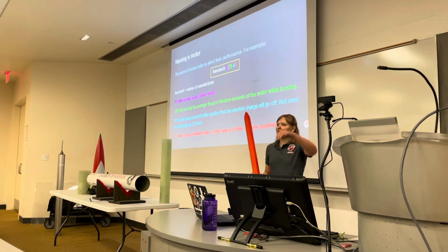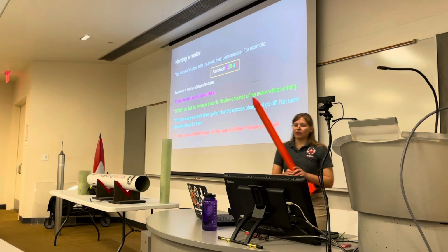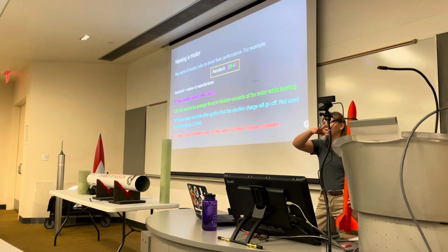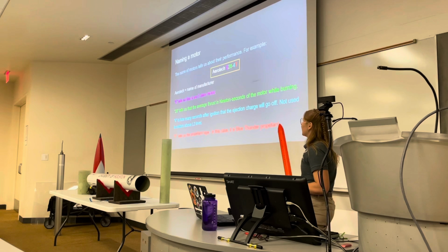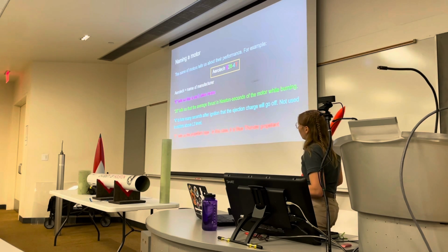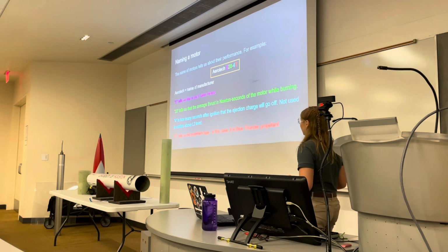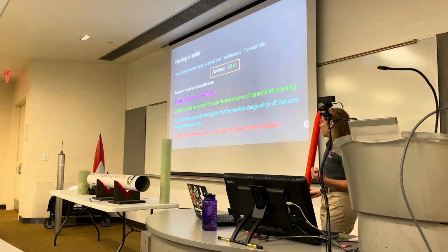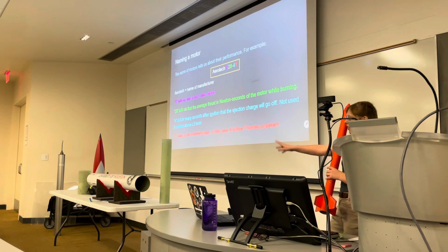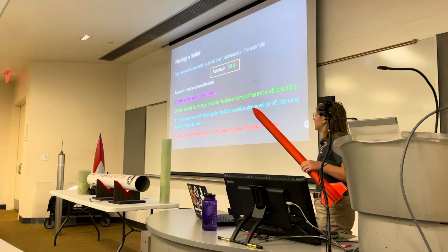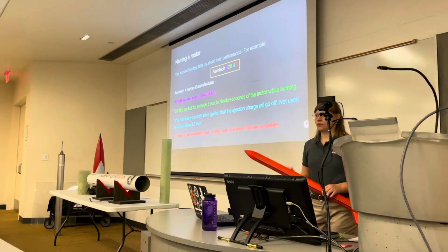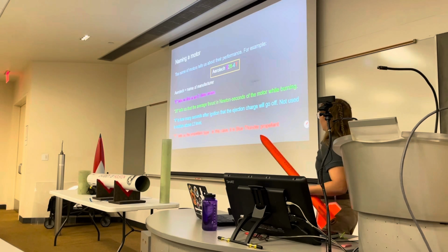So this is slightly different than your peak thrust. This is the average. So if they drew a line through all of the points on that thrust curve we talked about, right? That's your average thrust. 4 is how many seconds after ignition that the ejection charge will go off. This is not used in motors above L2. So this goes into a recovery system that's really not applicable to our type of rocket. But if you do your L2 or your L1, you're going to want to know about this. Only applies to little motors. So once we get into the big M-class motors, you don't need to worry about that.